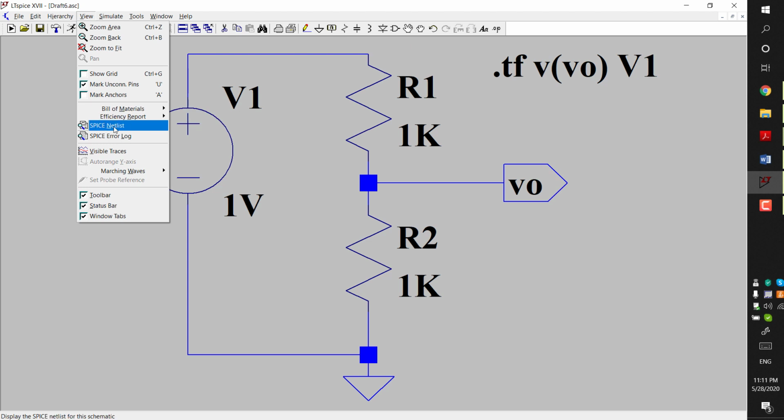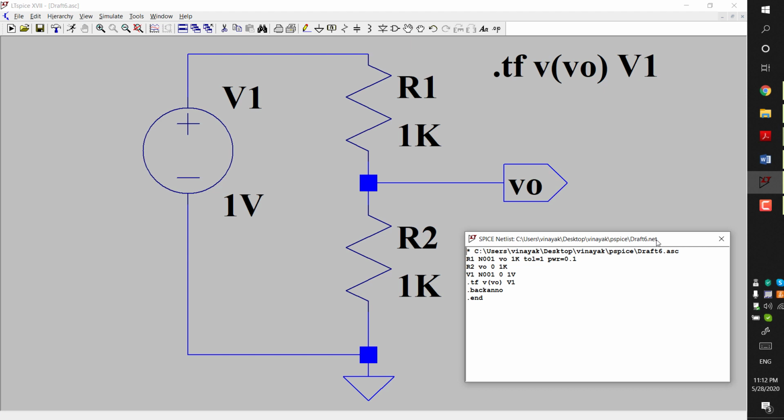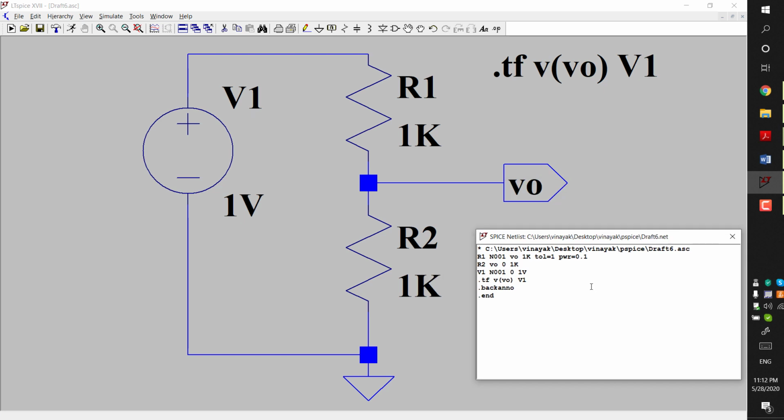If you want to design a circuit and simulate it, one way is to use circuit simulating software such as what is being shown and draw the schematic by choosing components and devices from the library. Another way is to create a blank text document, such as in MS Word, or we can use notepad, and on that blank page we can type the spice netlist such as this.